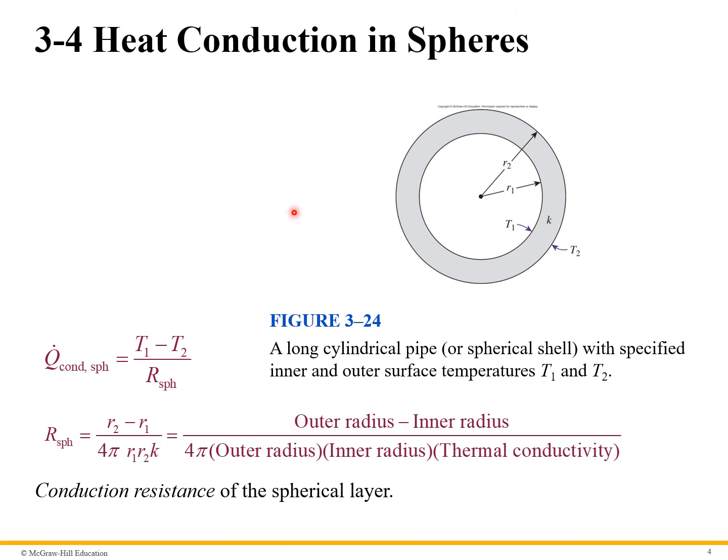We can extend this to spheres in an obvious way. We can do exactly the same thing we did before, and we come up with the following equation. In this case, our conduction resistance is given by the following formula.